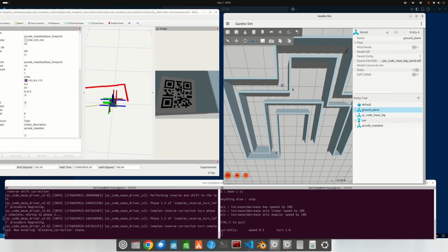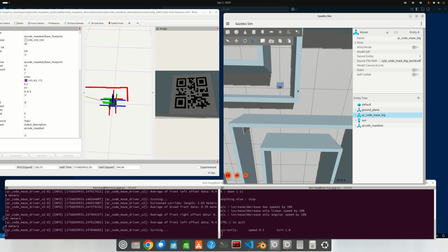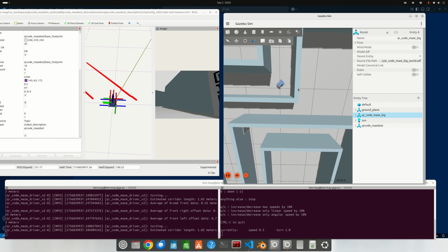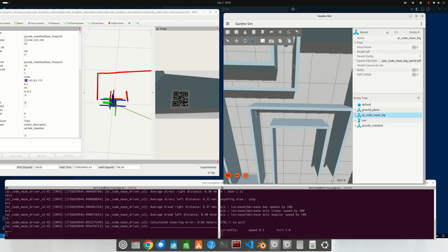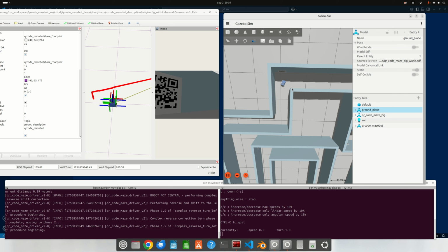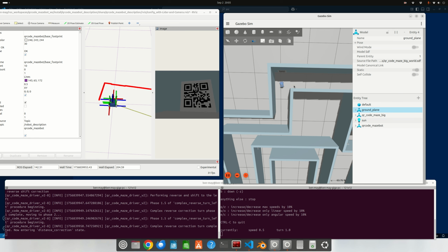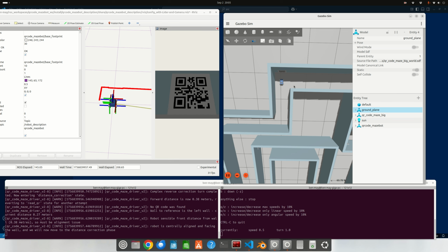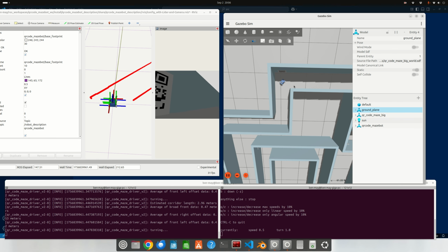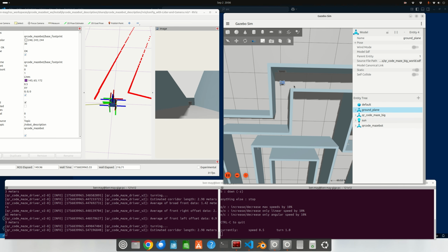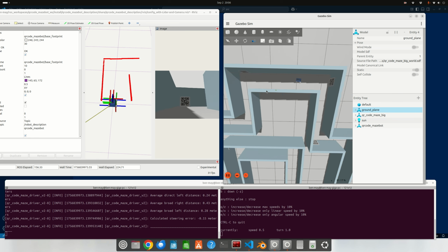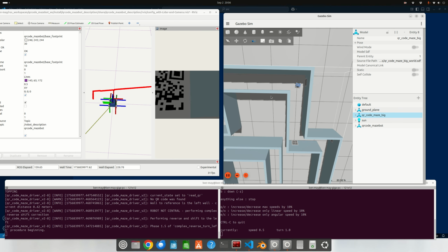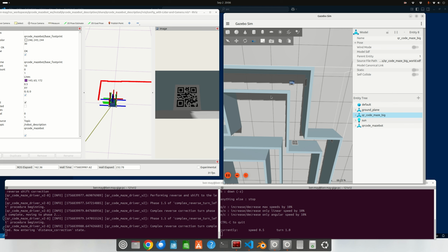And there is a solution to that. The solution, which is what I'll be doing next, is you can take the Lidar readings and put them into a Cartesian plane, so into an XY plane, and using a little bit of trigonometry plus an algorithm such as a RANSAC algorithm, you can create a line of best fit that represents each wall. And then because you know that a certain one of your Lidar scans represents the robot pointing straight forward, you can understand exactly how your robot is angled relative to the walls at any given time. And you then build that into the PID controller. So the robot is not only constantly assessing how far it is away from each wall, it's also constantly assessing what its angle is relative to the walls.